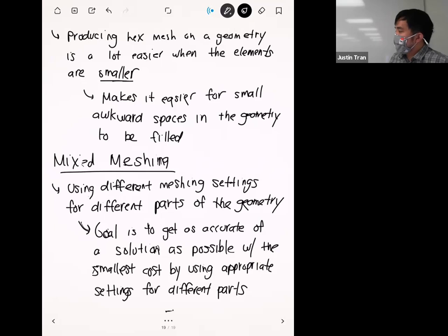And of course, this extends beyond element orders and element shapes as well, right? And so, just like we talked about in activity 3, this mostly applies to the mesh sizing. In the areas where you expect to see the highest stress concentrations or the highest solution gradients, that's where you're going to want to pack in most of your element density.